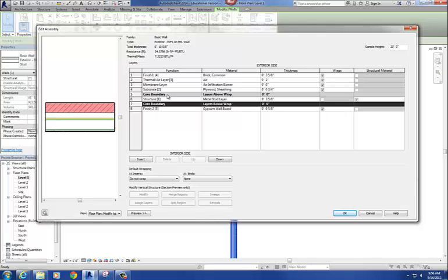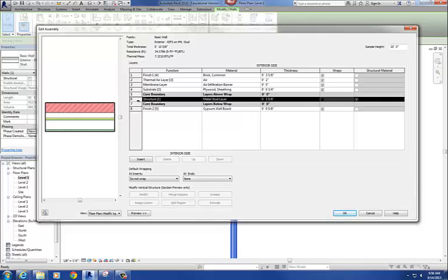To find out where that stud is. So what we do with the core is we define what the core is, and essentially the core allows us, when we're dimensioning, to dimension to the core, which is basically going to be the metal stud. So 99.9% of the time, the core is going to surround that first material that's put in when they're constructing that wall. All right, so that's my core boundary.